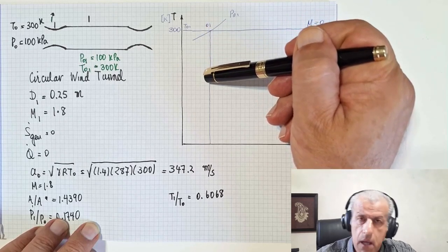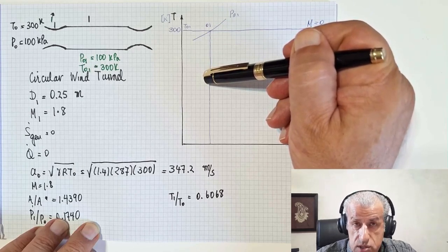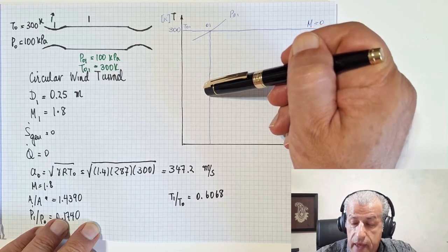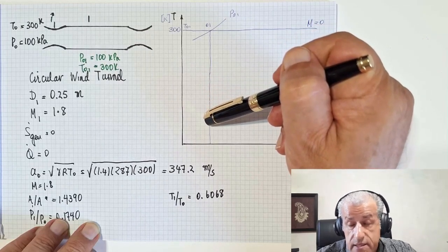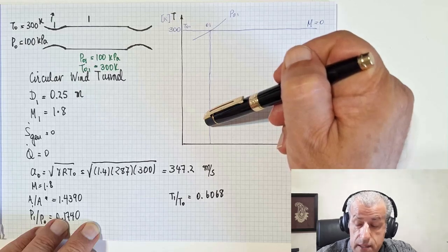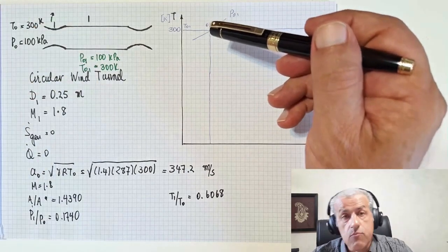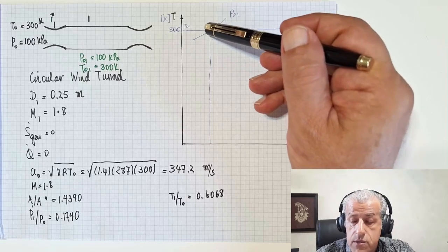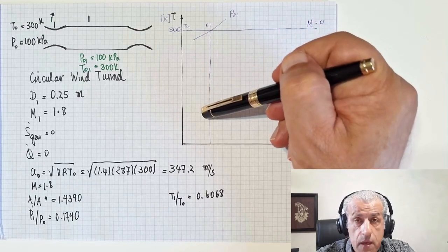Somewhere along the line, it comes to sonic velocity, which is the throat, which I'll show where it is in a short time. And then it continues to supersonic velocities up until somewhere here, where Mach number would be 1.8, and therefore the exact flow that physically moves along the supersonic wind tunnel would also move down along the isentropic line here.